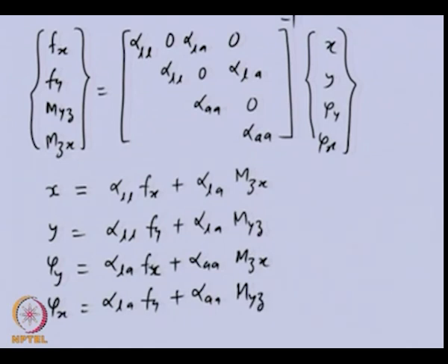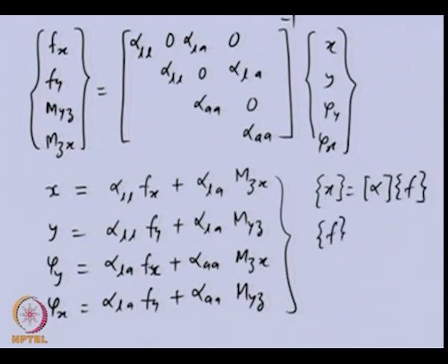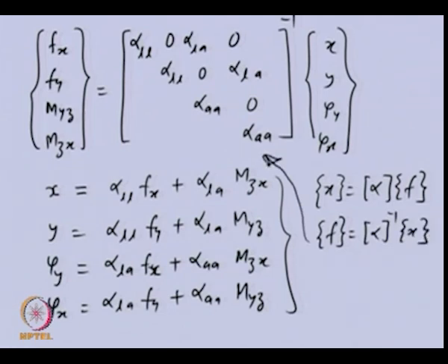So, basically we can put these in a matrix like displacement, influence coefficient and the forces. Then this force we can get by inverting this influence coefficient matrix. So, basically this equation is the above one, in which this is force, this is the inverse of the influence coefficient and this is the displacement vector.